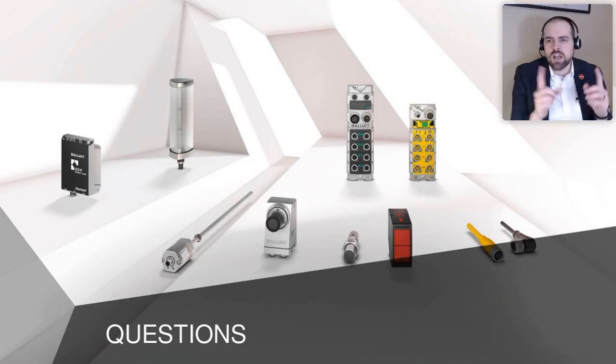Okay, thank you, Will. Chris, I want to add one more thing to that. If maybe an industrial controller isn't an option and you want to try to run a black box or an industrial hardened PC or something like that, there are ways to do JSON objects and REST APIs and UDP type traffic, just basic Ethernet type traffic. There are solutions for doing that as well.